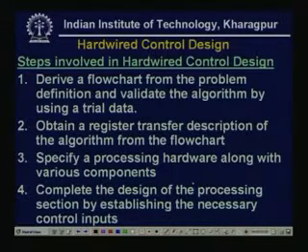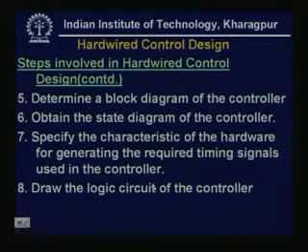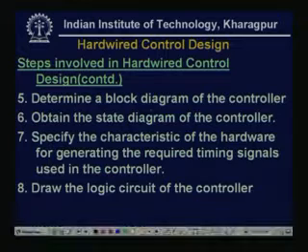That means, what input is needed to interface between the components and the processing section. Then step 5, determine a block diagram of the controller, because we want a hardware design. So, first the controller block diagram level design we have to do. Then step 6, obtain the state diagram of the controller.